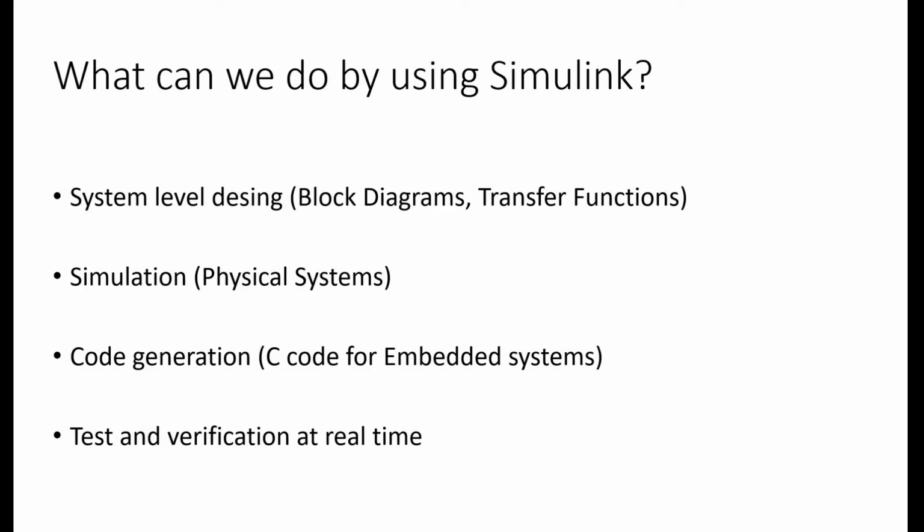You can generate C or C++ code for embedded systems, for DSPs, with the help of Simulink. You can test and verify the constructed block diagrams in real time. This is a very interesting option of Simulink. You can connect a real physical system, for example, a power electronic device, to your computer and do a hardware in the loop simulation where you take data and give data to the power device and control this device in real time.